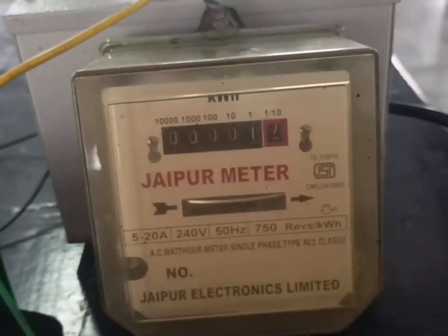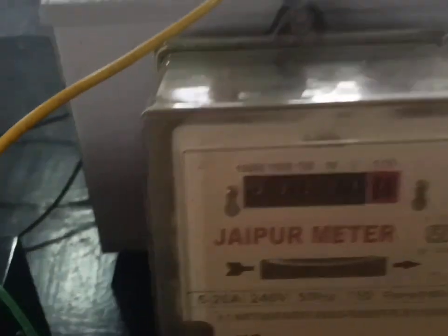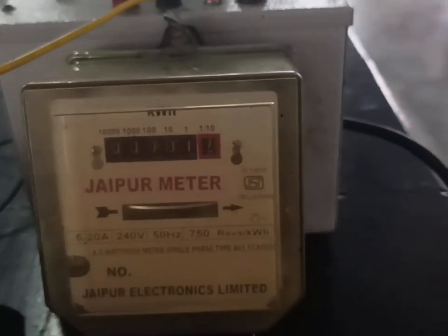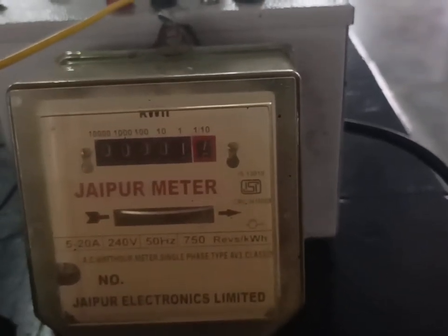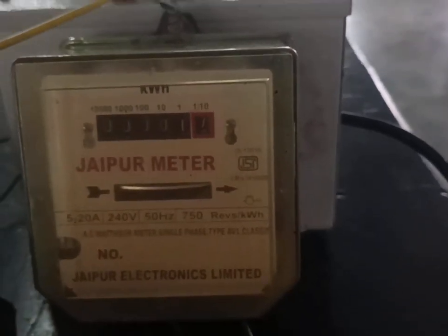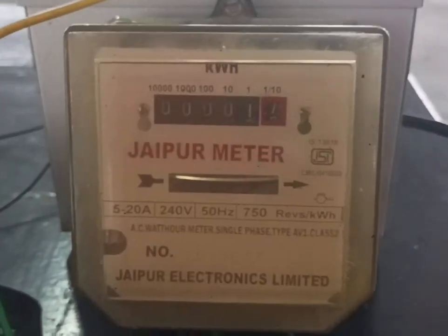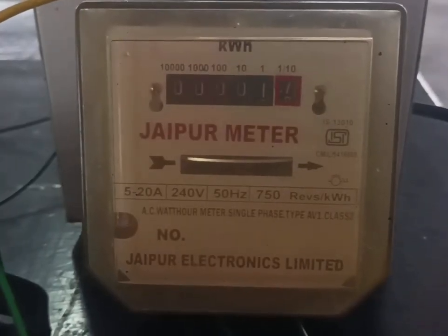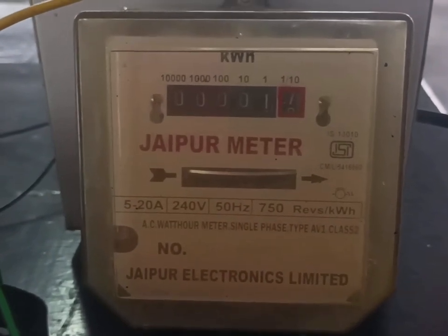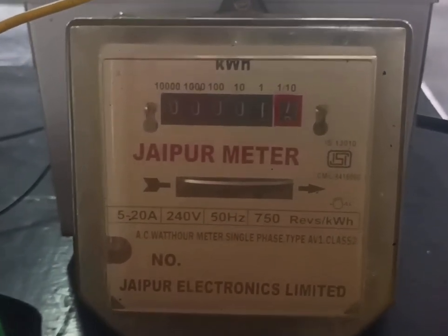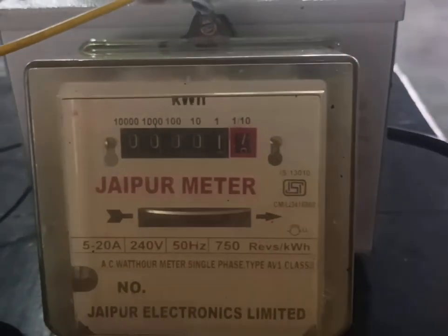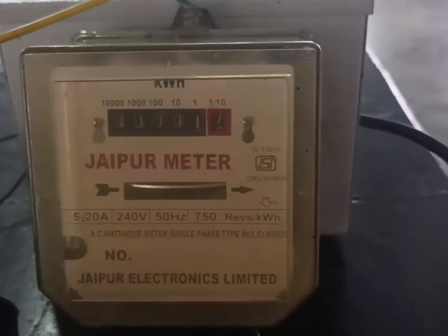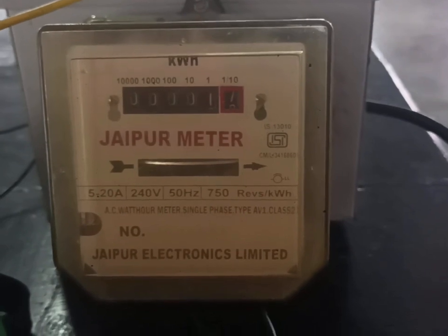This is the experimental understanding. In conclusion, when the load increases, the watts and amps ratings increase, and the energy consumption and energy meter disc rotations also increase, while the voltage rating only drops. When the load decreases, the watts and amps ratings drop, the voltage gradually increases, and the energy meter disc rotation speed drops. This is the conclusion of this experiment.